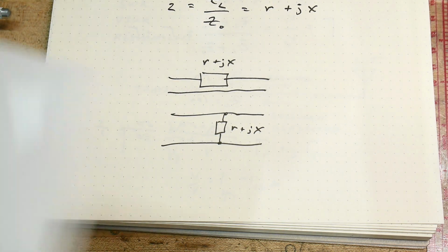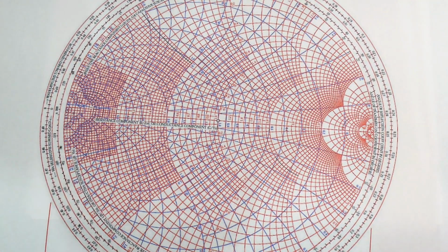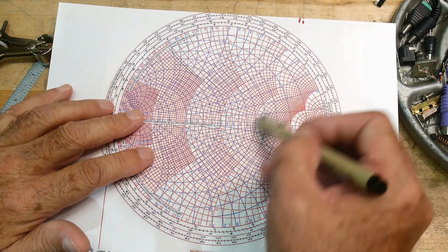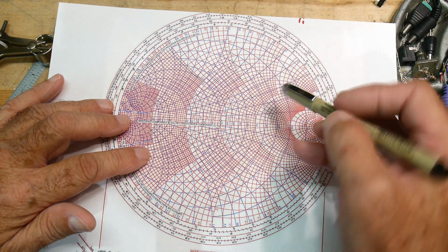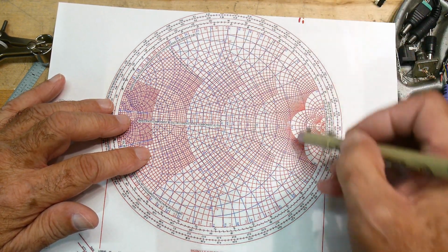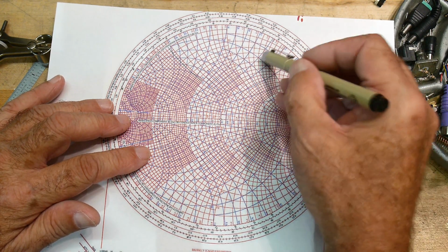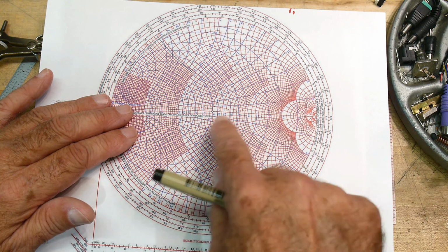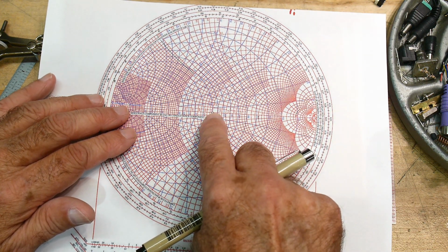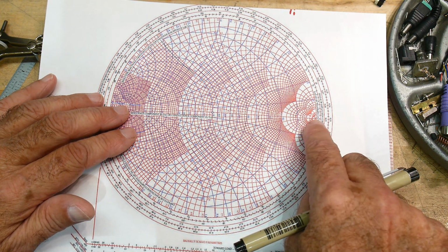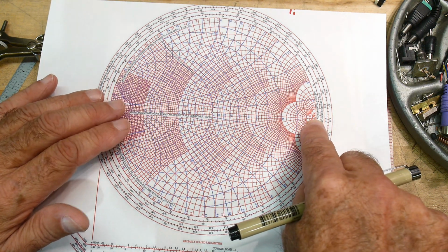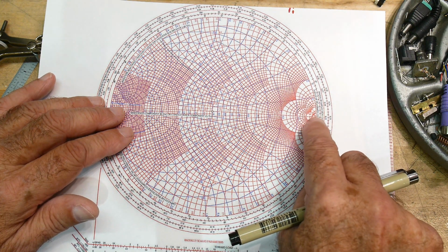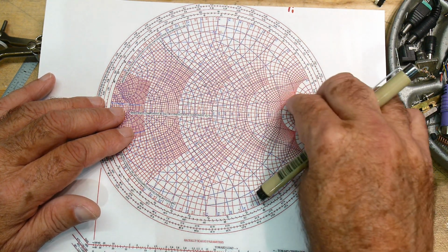So let's go back to the Smith chart. And we can see those curves that we just plotted in red, okay? The red ones go here, and then the red ones also go here. And those are all of the cases where we are in series. We can start at the center, and then we can go here to this point, which if you have a VNA, you know this is the open. When there's an open, you get to here, okay? So everything can go to an open.